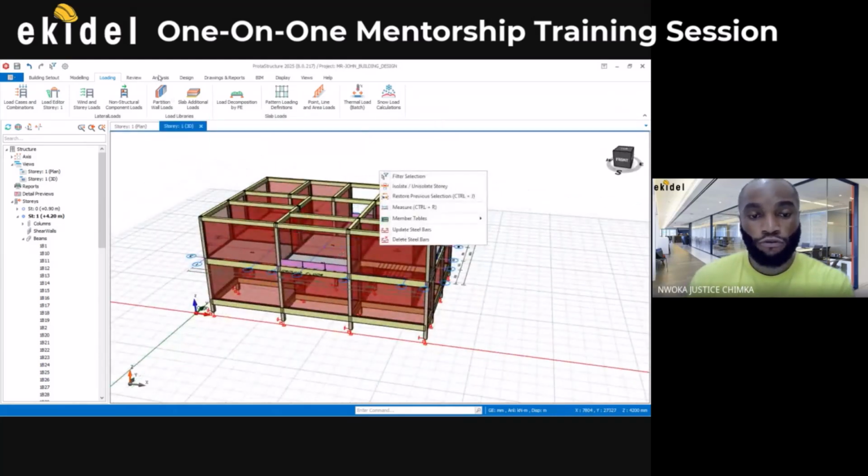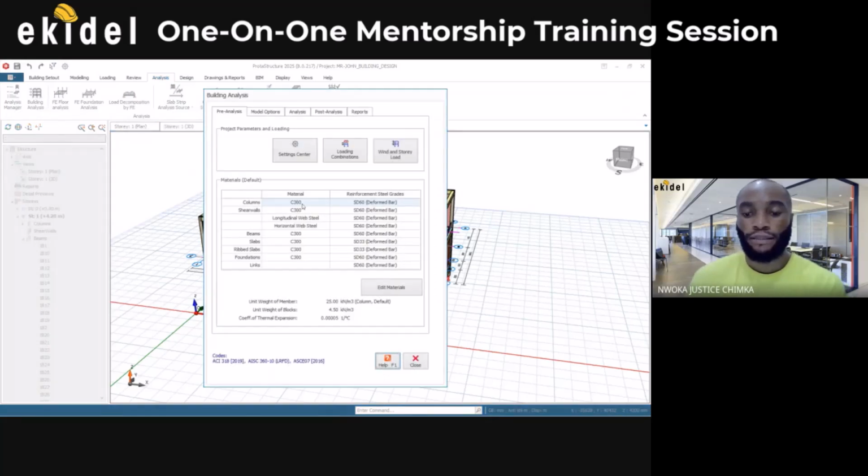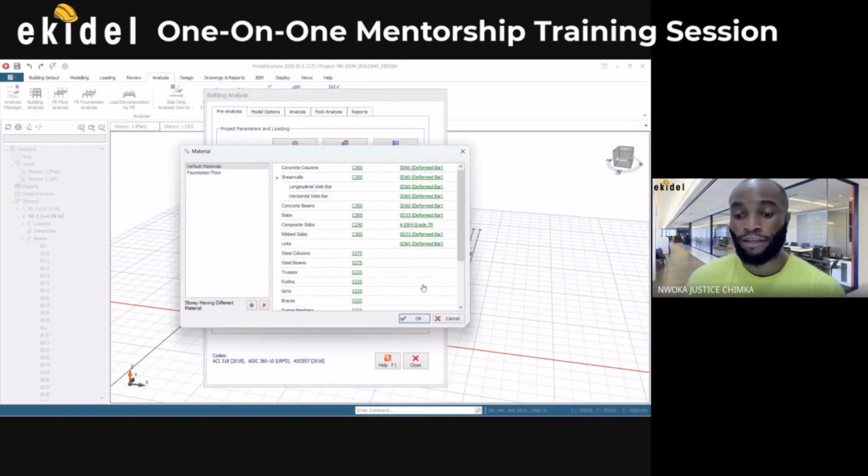So now click on the Analysis tab here. Then under building analysis, click on edit material, for us to choose our concrete grade and our steel grade. Edit material there.